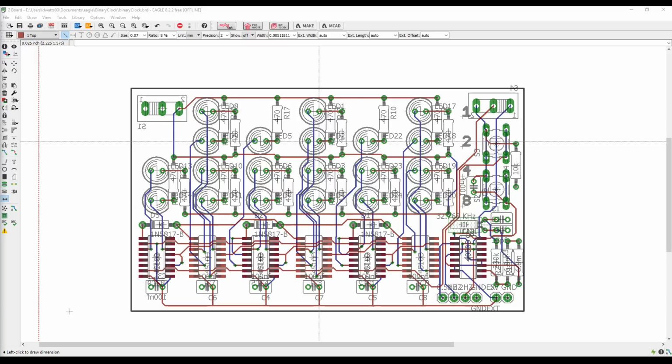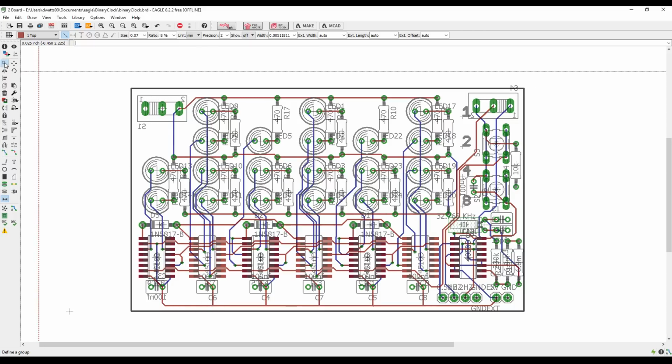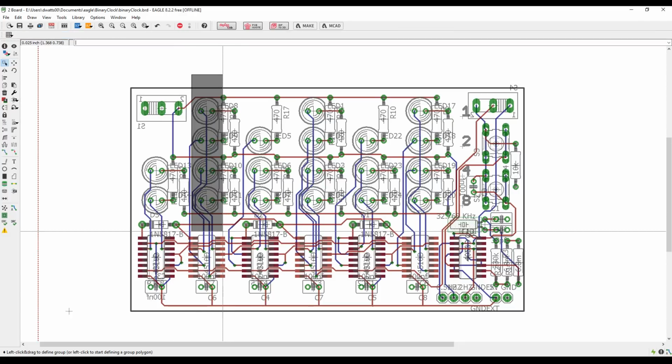Oh, and he also asked, what type of binary counter is it? Can it be a bedside clock? Yeah, essentially it is a clock, and it's not really strictly a binary clock because it's doing 4-bit binary for each one of these bits. So each one of those bits there, that's 4-bit binary. So it will start at the bottom here, that is 0, that'll be 1, 2, 4.